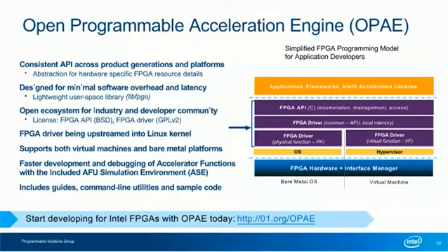The OPAE technology supports both virtual machines as well as bare metal OS platforms. The OPAE technology is also fully compatible with the AFU simulation environment, which allows you to simulate the interaction between the OPAE layer and the FPGA in an industry standard simulation tool even before the availability of the FPGA part. Lastly, OPAE comes with guides, utilities, and sample code. For more information and links to the source on GitHub, please visit 01.org/OPAE.